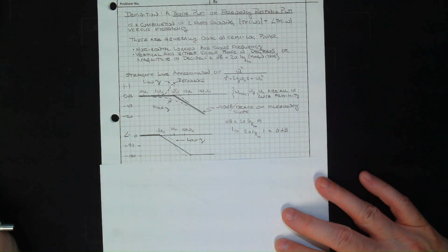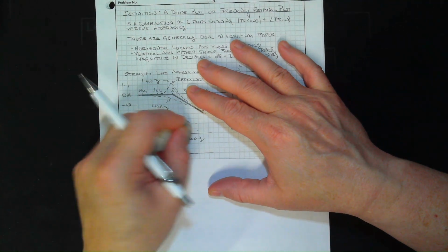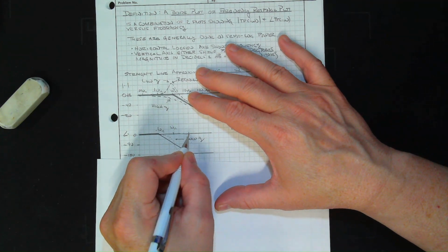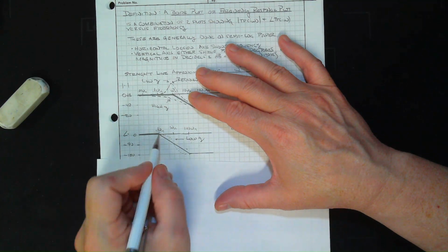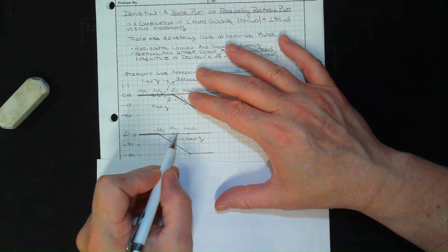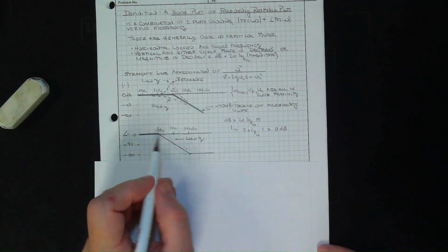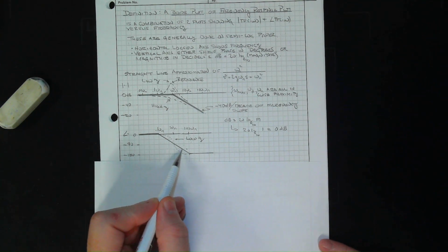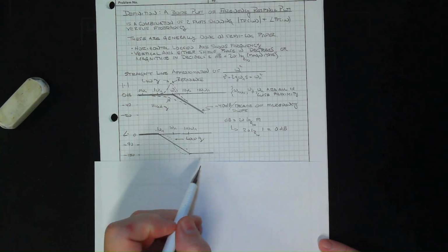And this is a little out of scale, I see in my drawing. So let me fix this. It's actually way out of scale, but it doesn't really matter all that much. We'll let this be 100 omega n. These should be evenly spaced, but, oh, they are now. Yeah, 1, 2, 3, 1, 2, 3. That works out. All right. So here we are at 10 times the natural frequency. In this decade, we lose the other 90 degrees, and then it levels out.